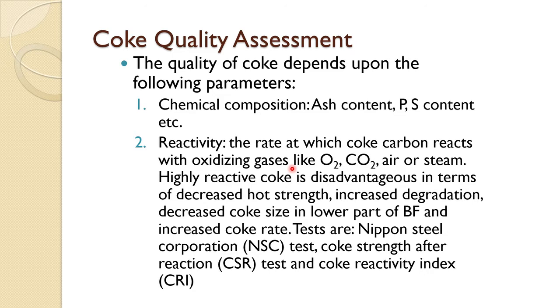So, what we need is not a very highly reactive coke, because in terms of design for hot strength, it increases degradation, decreases coke size in the lower part of the blast furnace, and that will also increase the coke rate. So, the tests are the Nippon Steel Corporation test, NSC, coke strength after reaction, CSR, or coke reactivity index.